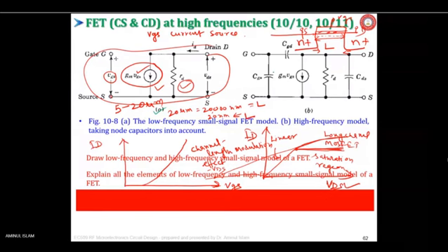If you take into account the capacitances, then they have to be included in the model, because I have shown that there are 5 capacitances, excluding the overlap capacitance as well as the drain diffusion and source diffusion capacitance, which are also not discussed.